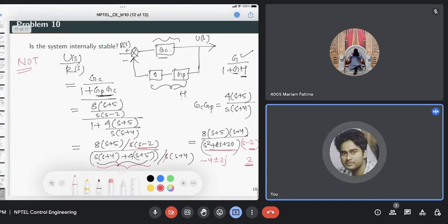We computed the transfer function from r to y, and to this internal signal u, and we see that this term appears there, right? So that will contribute a positive side pole. That means this system is not internally stable, right?